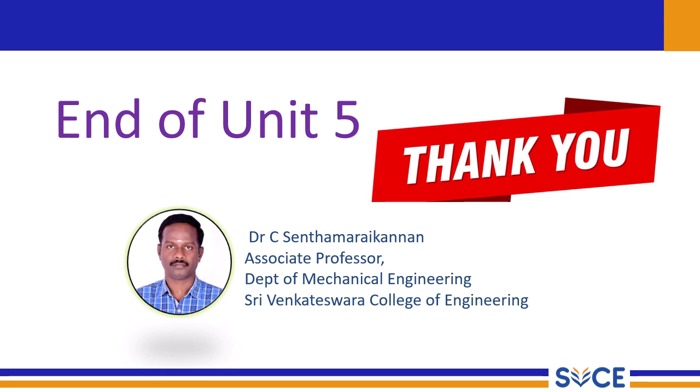We explored key methods for vibration control, including manipulating natural frequencies to avoid resonance, introducing damping to dissipate energy, employing vibration isolation to block transmission, and utilizing vibration absorbers to counteract specific frequencies. We discussed the principles and practical considerations for each of these techniques, including the benefits and drawbacks of different approaches like material selection, joint types, viscoelastic materials, and tuned mass dampers.